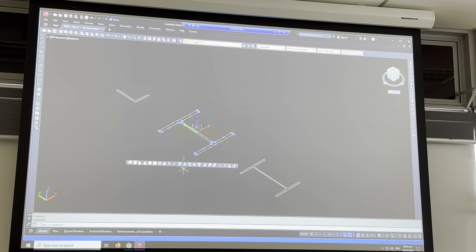I'll just check that. Yep, they are going to extrude. So if the ones that you bring in aren't P lines, make them into P lines. Would that just be selecting them all and joining them? Yes, if they're single lines. If they're a block, you may have to explode it first and then join them.